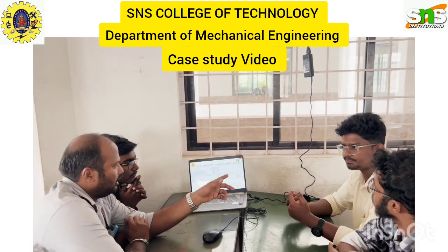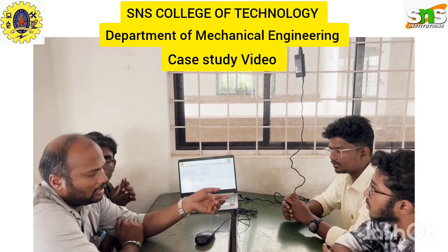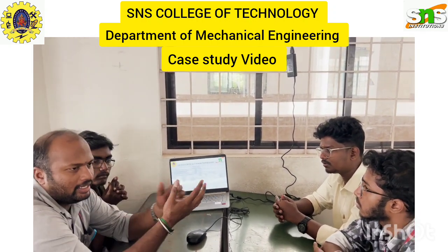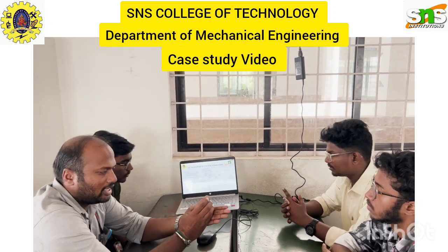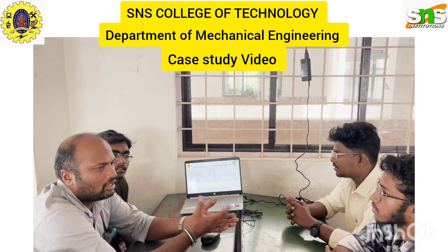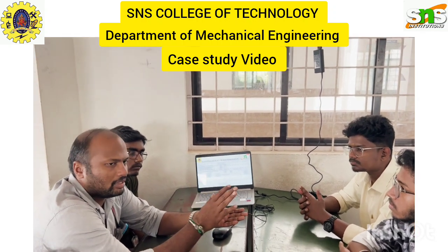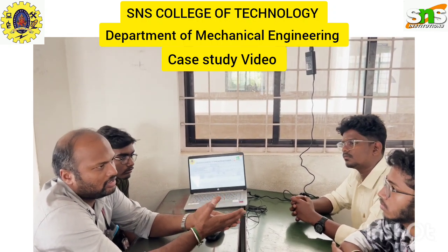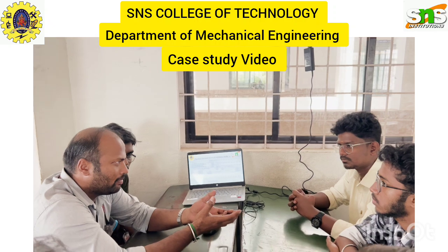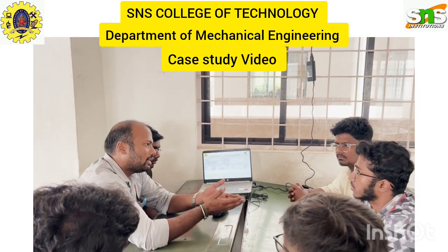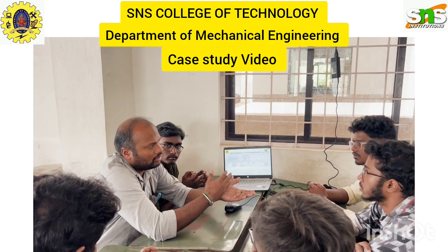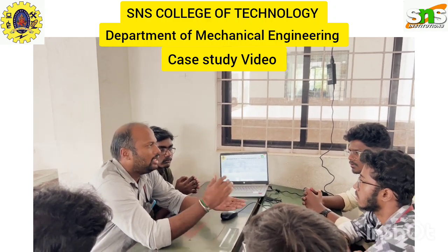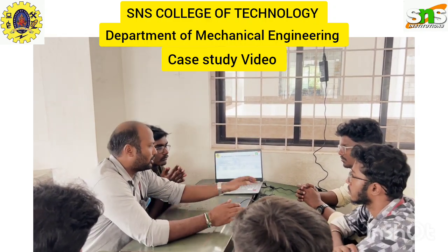Adding to this, if a material fails, we must first check the chemical composition, as he said. If the chemical composition is not right, it should be rejected at the first investigation result. Sometimes failure can occur due to the chemical composition. If the chemical composition is altered, there is eventually a change in the mechanical and metallurgical properties.